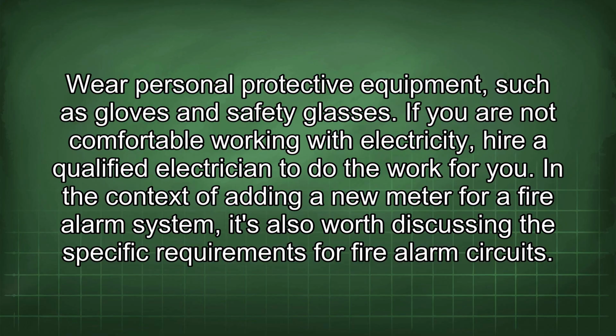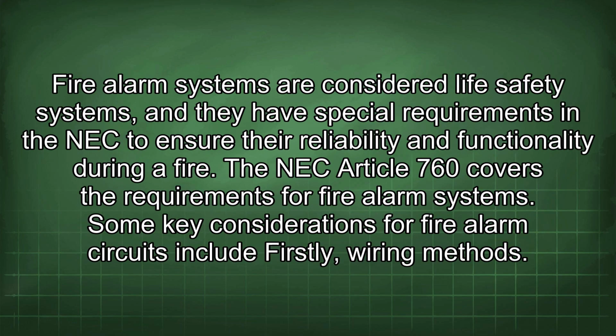In the context of adding a new meter for a fire alarm system, it's also worth discussing the specific requirements for fire alarm circuits. Fire alarm systems are considered life safety systems, and they have special requirements in the NEC to ensure their reliability and functionality during a fire. NEC Article 760 covers the requirements for fire alarm systems.